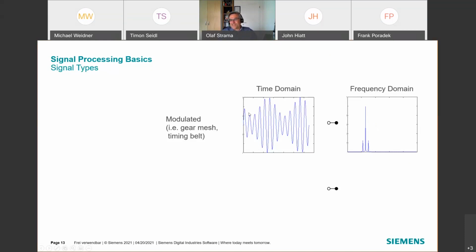The modulation is a multiplication. I multiply the carrier with the modulation signal, then I get this typical shape. And this multiplication leads to a convolution. If I have lines in the spectrum, then I can solve this convolution integral. I have a lot of zeros in this integral if I talk about harmonic and periodic signals. At the end, it looks as if the modulated signal is shifted around the carrier. And so the distance of this line from the carrier shows the frequency of this modulation.